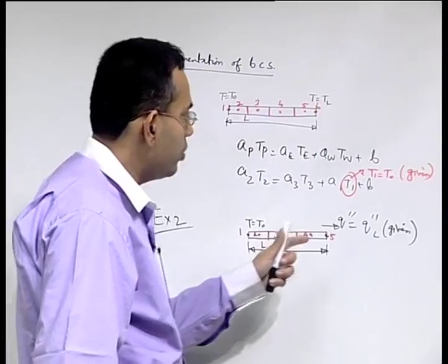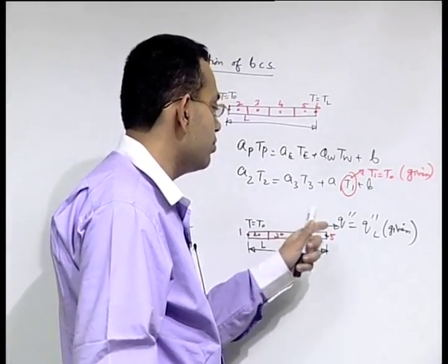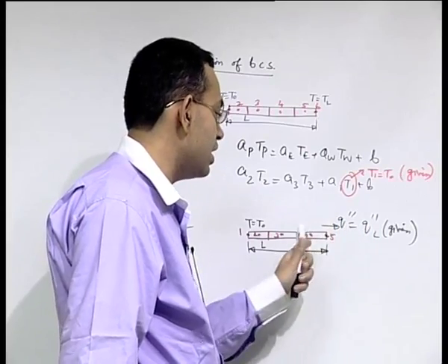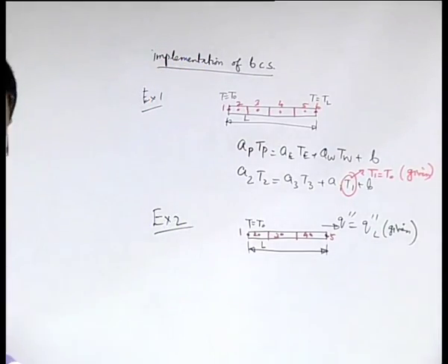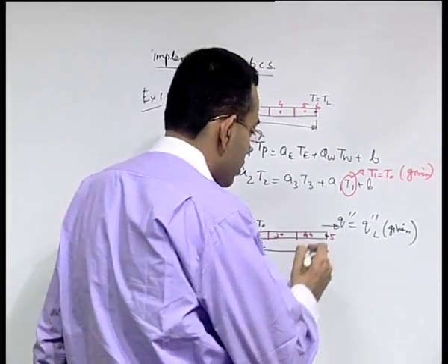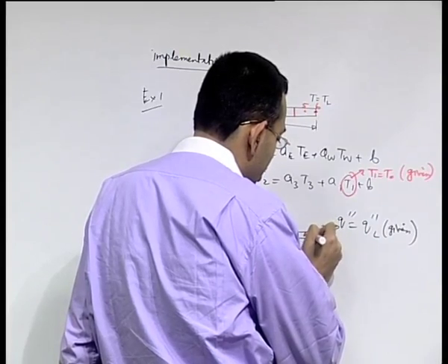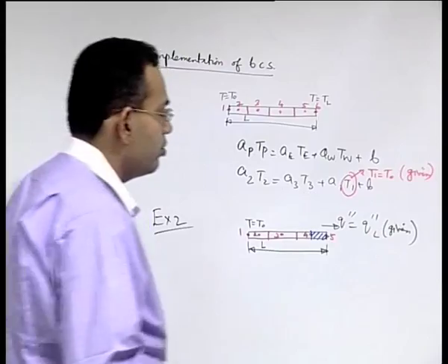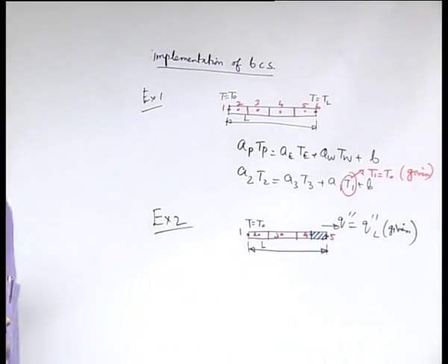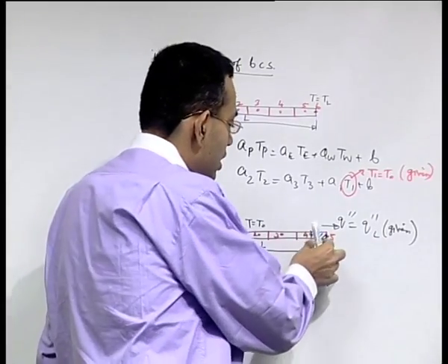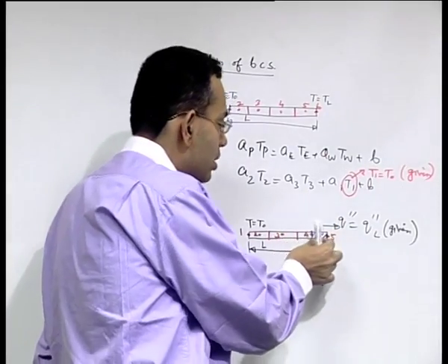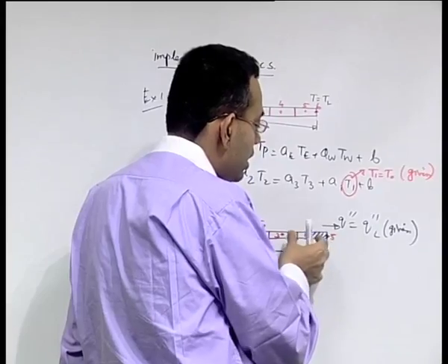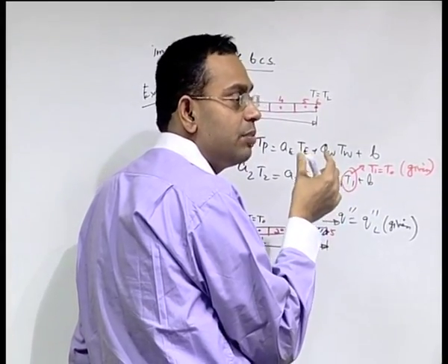Now, to implement the boundary condition, which is given in terms of the heat flux here, we have to consider a control volume at the boundary. Sometimes one may take half of a control volume, one may also take a full control volume, but if you take half of a control volume the boundary condition is more accurately implemented, because if you take a greater extent of a control volume your gradient approximation becomes weaker and weaker.